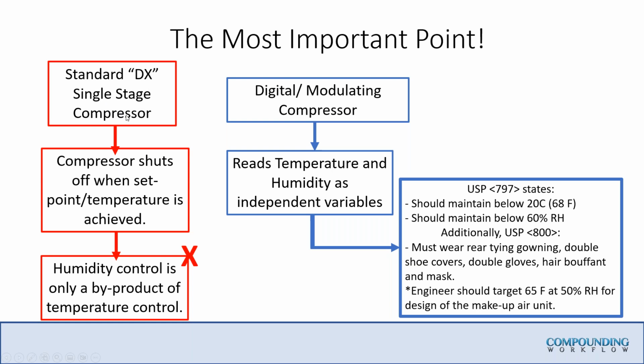Now, a single stage compressor unit is exactly what you have at your house, or in a small strip mall or any type of commercial strip mall. That means that when the thermostat reaches that design point or set point, let's say you're running it at 71 degrees today, and when that thermostat detects that the environment is 71, it sends a signal back to the air handler that the compressor can cut off. When the compressor cuts off to stop managing the temperature, it also